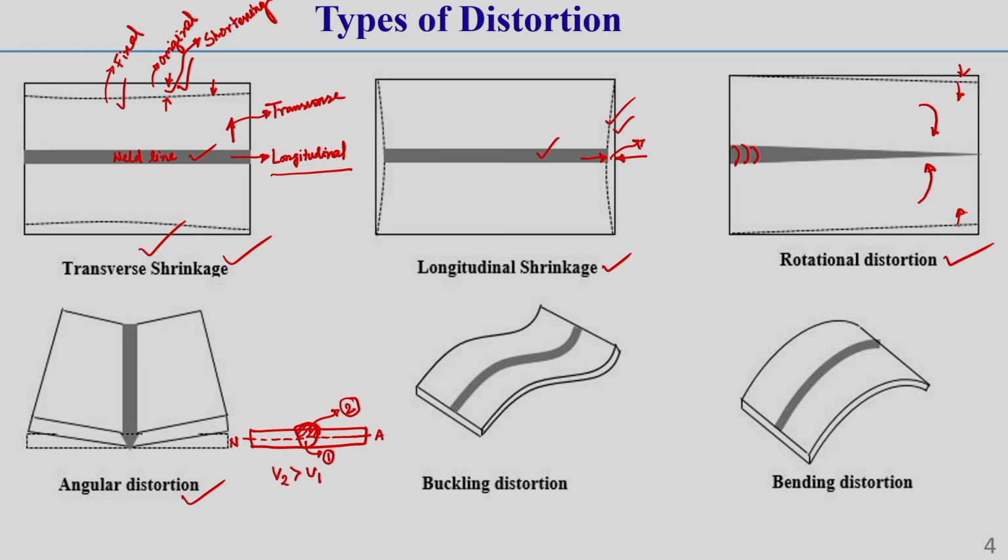Now, once this material solidifies, then this volume of molten material loss, or you can say weld material loss, is higher generally on the top side, and this will create some shrinkage force. So, shrinkage force you can say is proportional to the volume of material solidification. What I am telling, understand? So, the higher the volume of material solidification, the higher will be the shrinkage force.